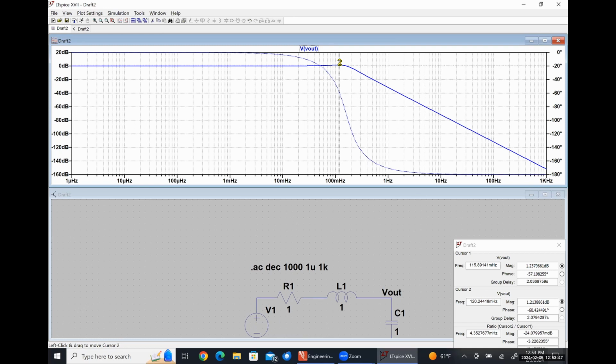So on our first order filters and our band pass filters and our band stop filters, where everything was rolling off like it was a first order thing, so everything was rolling off at negative 20 decibels per decade, we didn't really have to worry about anything like that because our maximum value was always 0 dB or 1, right? Here, because we have that uptick, that's what's skewing things a little bit and why our minus 3 dB frequency isn't something that looks like we've seen it before. All right.